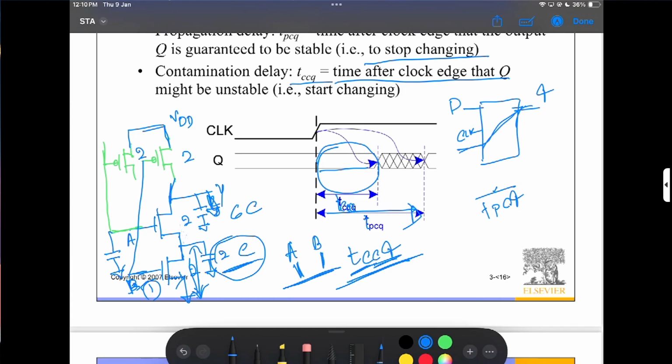What happens is this charging delay, where here is my R and here is my R. So 6C times R by 2, plus 2C times R by 2, so basically 7RC. So this is the time required for propagation.